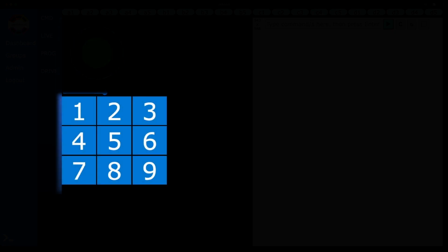The slider underneath the joystick controls the sensitivity of both the keyboard and the joystick itself. By default, the sensitivity will be at its maximum. If you wish to reduce the sensitivity of these controls, slide the slider towards the right-hand side. When it's all the way to the right, the sensitivity is at its minimum. What this means is that when the sensitivity is lower, the robot will move more slowly in response to the controls.